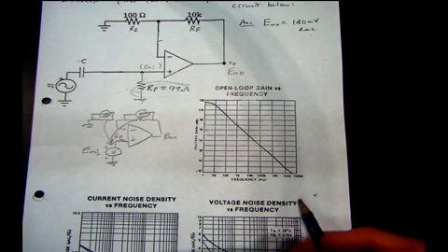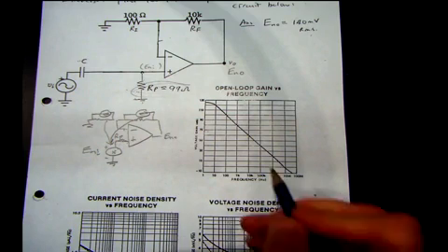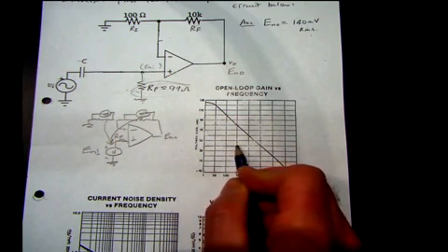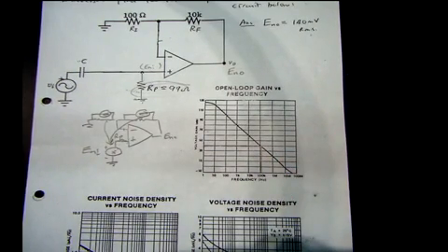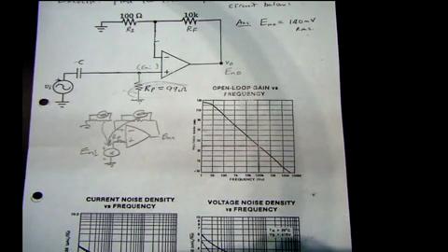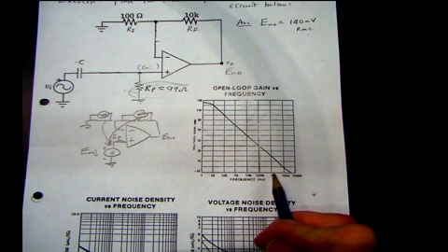Do you remember we worked out the gain of this was going to be 40 dBs, was it? Is that right? And so we figured out what the signal bandwidth was. That was 100 kHz. And so a conservative estimate of the noise bandwidth was pi on 2 times that signal bandwidth.